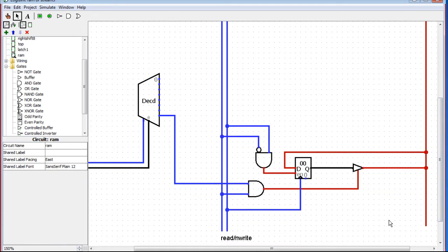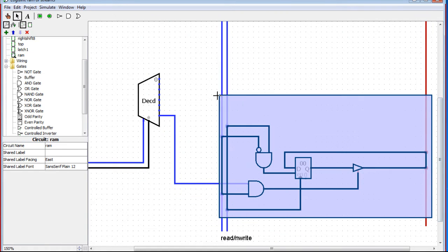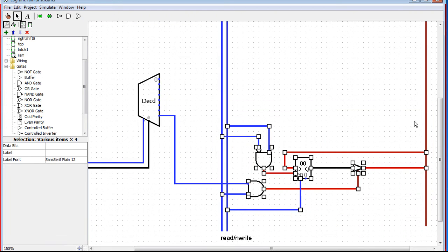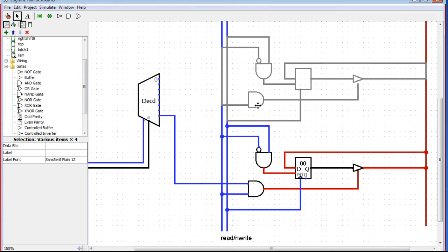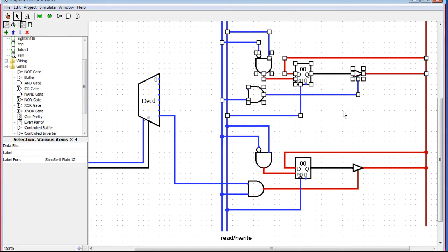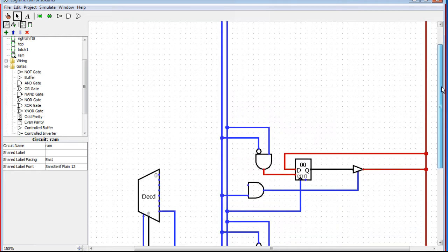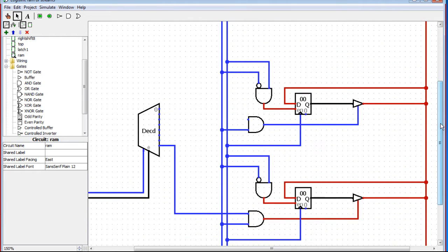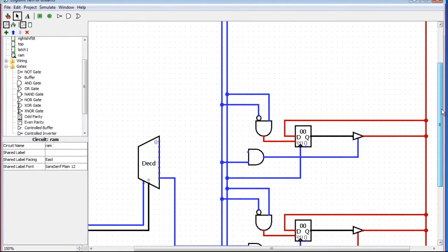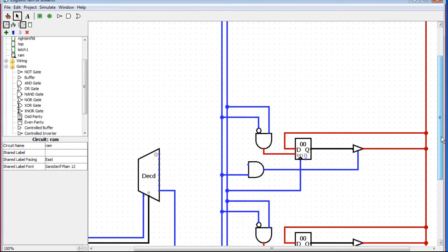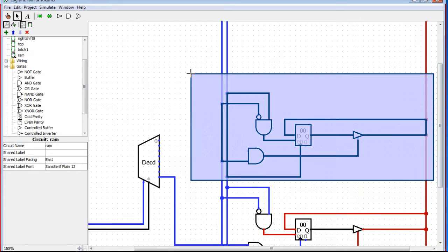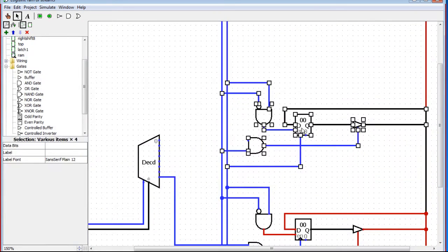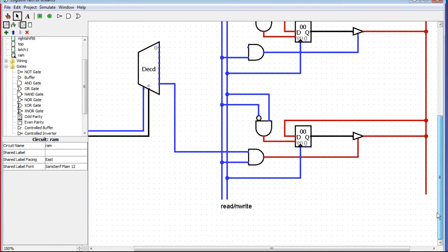So we take our bulk RAM, the stuff that we generally call RAM, and we build that out of dynamic RAM, DRAM, and it's slow. And then for the really fast cache, we build that out of flip-flops. We put that right on the die with the CPU. But in this program, everything runs at the same speed. There's no limitation on speed, so there's no reason to make a cache from a memory speed point of view.